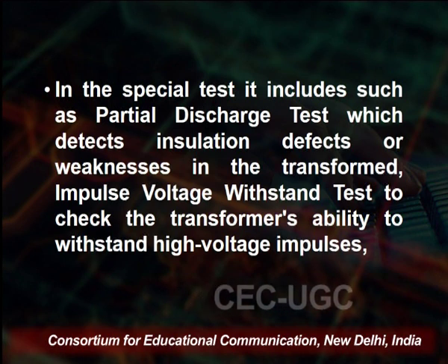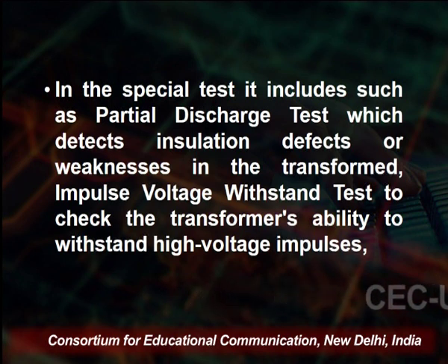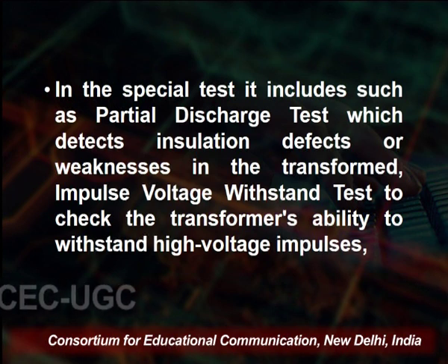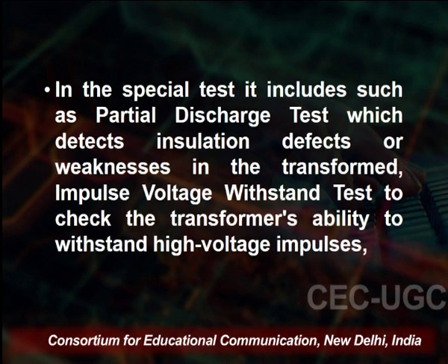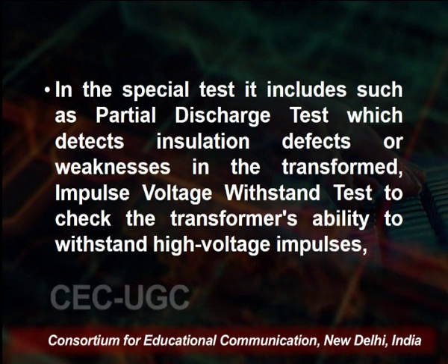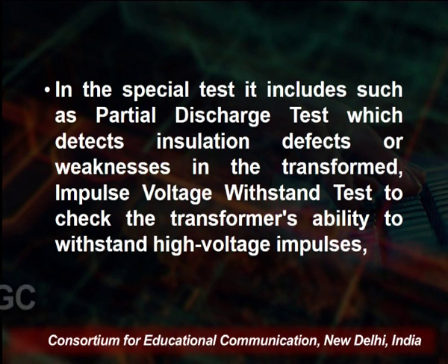In the special test, it includes such things as the partial discharge test, which detects the insulation defects or weaknesses of the transformer. The impulse voltage withstand test checks the transformer's ability to withstand high voltage impulses. Frequency response analysis detects mechanical defects or winding deformation in the transformer core and winding by checking their frequency response to a frequency signal.